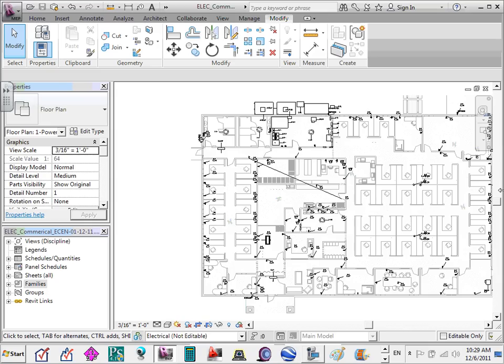I'll show you later on, one of the most important things when you bring in your model is you have to pin the model to the view. If you don't do the pin, can you guys see that under modify, unpin and pin? You have to grab the model and pin that model, meaning if Chris comes and accidentally drags the whole building this way, the building will be here and the equipment will be sitting right there. That's a big thing. When we bring in the model, we pin the model right in here. We don't want it to move anywhere. We can look at it, but we don't want it to move.